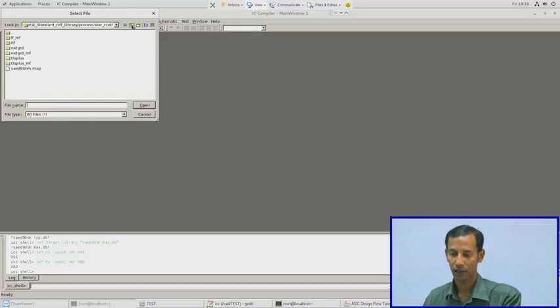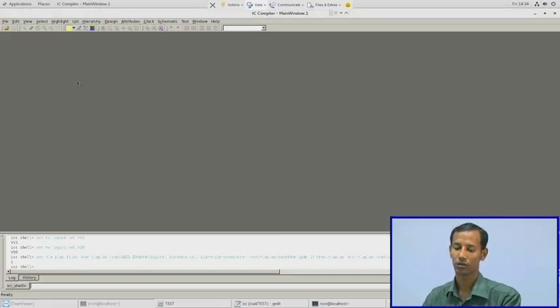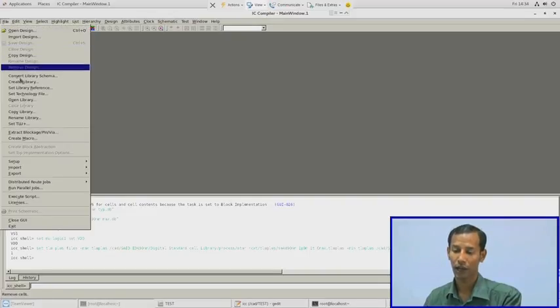Again that will be found in the Astro folder. In the Astro folder, within the tech directory, you will find the tech to ITF map. You just click on this, then choose this. You can also do it by command line. Whatever I did in GUI mode, for that you have to mention or write this command.